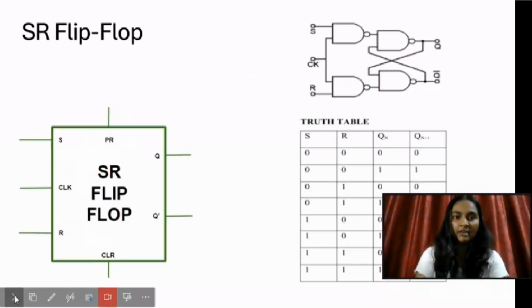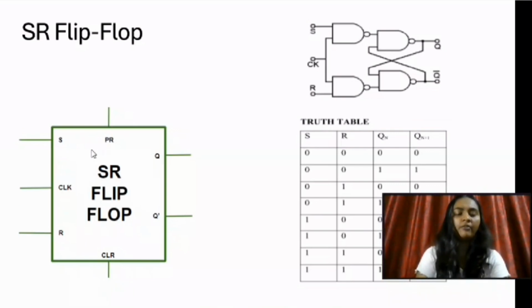To know what an SR flip-flop is: in the flip-flop, with the help of preset and clear, when power is switched on, the state of the circuit keeps on changing. That is uncertain. It may come to set state Q equals 1 or reset state Q equals 0. In many applications, it is desired to have an initial set or reset of the flip-flop, that is, the initial state of a flip-flop needs to be assigned. This is accomplished by the preset or the clear.